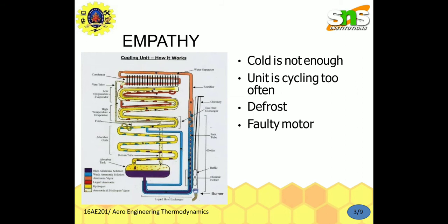In the early years of the 20th century, the vapor absorption cycle using water-ammonia systems was popular and widely used, but after the development of the vapor compression cycle, it lost much of its importance because of its low coefficient of performance. Nowadays, the vapor absorption cycle is used only where heat is more readily available than electricity, such as waste heat provided by solar collectors or off-the-grid refrigeration in recreational vehicles.